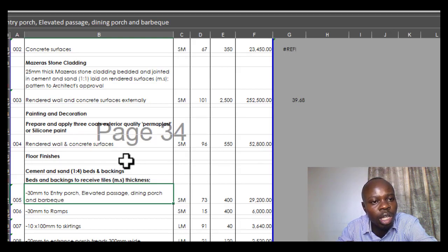You've mentioned the thickness of that given screed, and to some extent, especially when the rooms are divided or have different types of finishes, you can do your separation and mention that here and there. But it's not so much described in the rule that you have to identify the spaces; you have to identify the type of finishing that is done in a particular place or in a particular area.